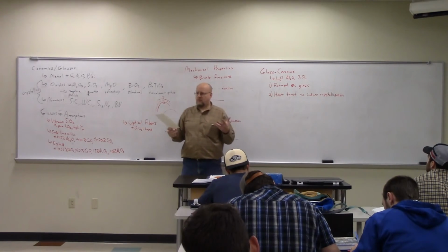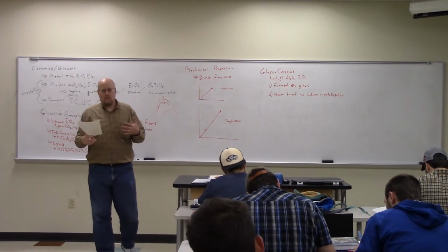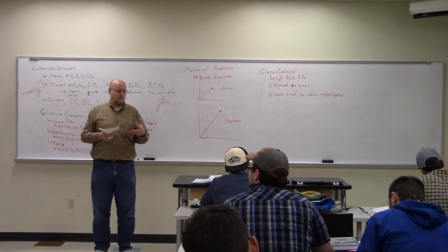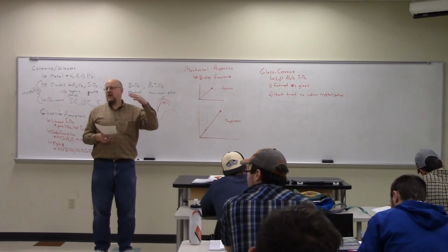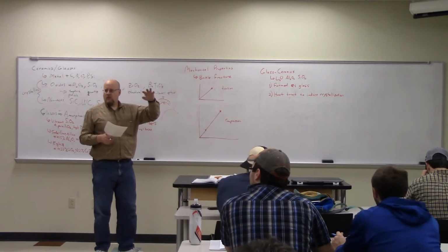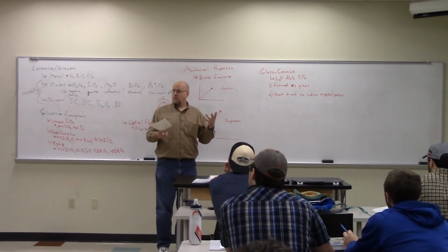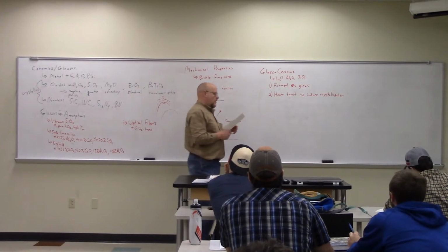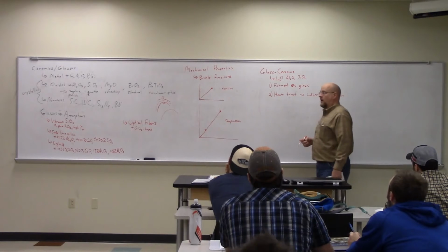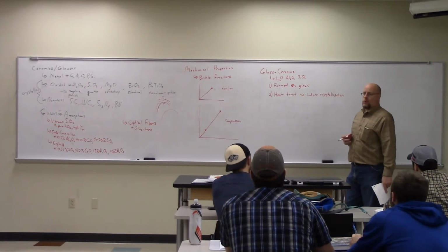So we've got this glass, it's amorphous. We've probably had some kind of rapid cool at some point to allow it to stay amorphous at room temperature. But then we heat it up once it's in its shape and allow it enough time at that high temperature to crystallize, because the crystalline form is the preferred, equilibrium form. Isn't glass stronger though? No, typically the crystals are stronger than glass. Quartz is stronger than the glass window.